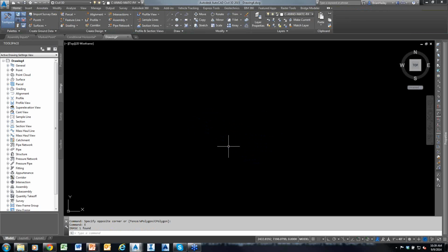All right, so Sheldon, I'm assuming you need to do a 3-line profile. I have my center line alignment, I've got my flow line alignments, they each have their own profile, and I need each one of those components to follow along that. So here's the approach I would do. I would create generic links that go from the center line to those offset alignments and profiles. And then to that, I would attach my curving gutter. And then from that, I would attach lanes that then target back to the center line alignment and profile.